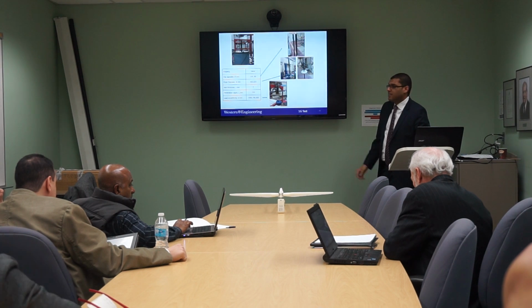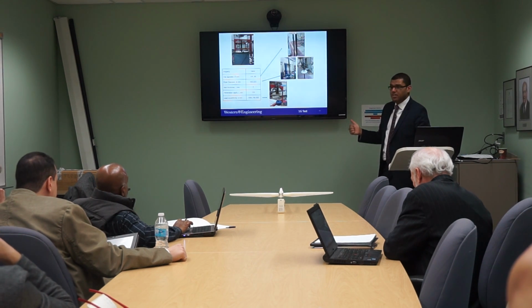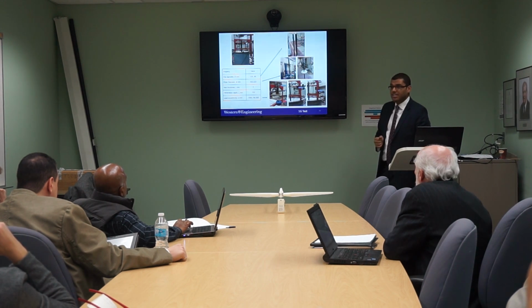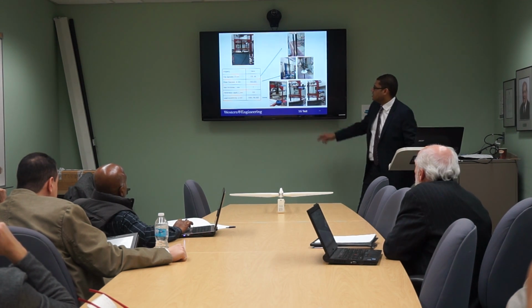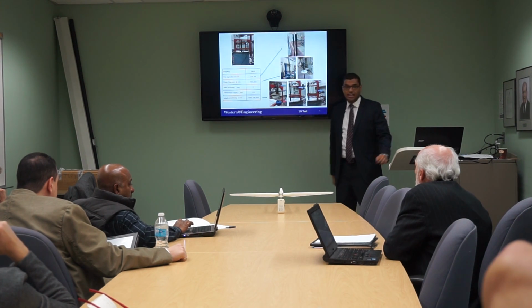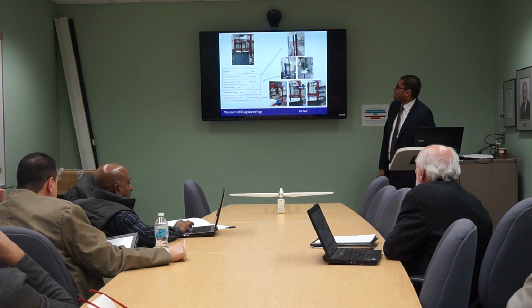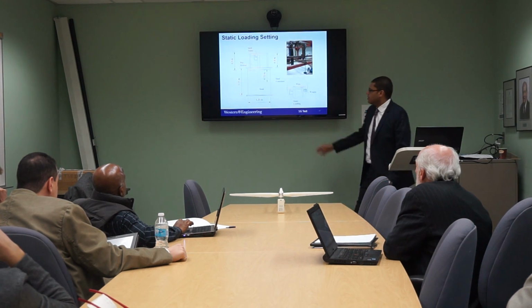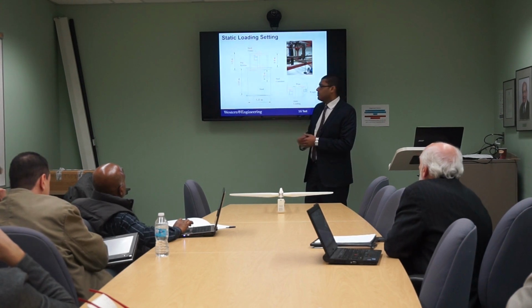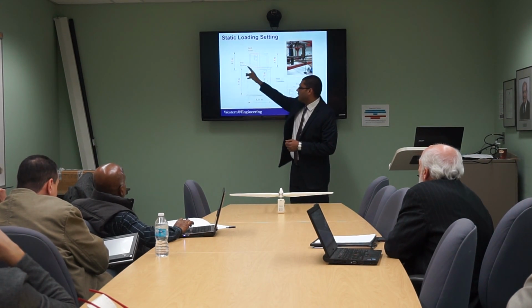For static load, we have done 1 meter eccentricity, 0.75 meter eccentricity, and 0.5 meter eccentricity. As you can see here, this is the wire, this is the pulley, and this is the load to be able to add load during static testing. This is a cross section of our model, which is the steel tank with diameter 1.35 meter and depth 1.5 meter.